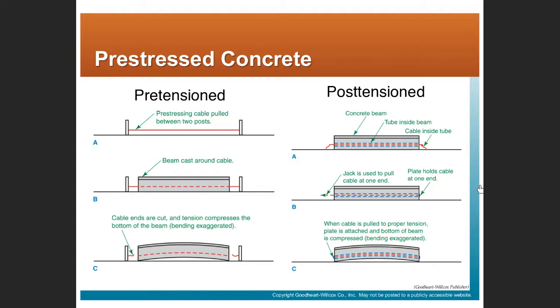But again, I think the danger with pre-stressed concrete is that all the other trades on the job have to know where that cable is in the concrete, or else they're going to have a nasty surprise if they hit that thing with a hole saw when they're trying to drill something.